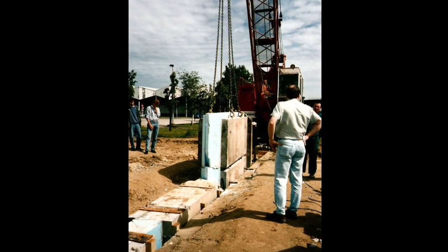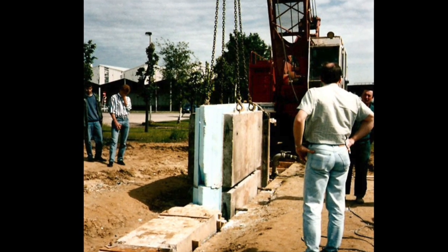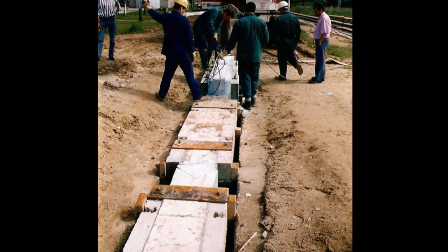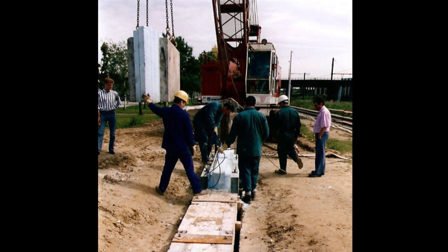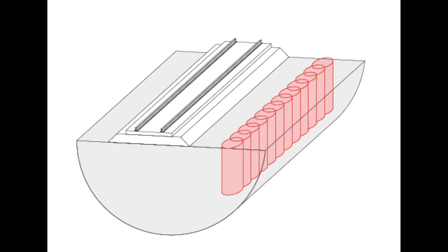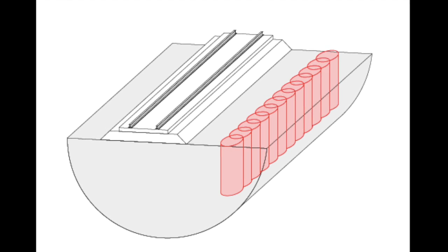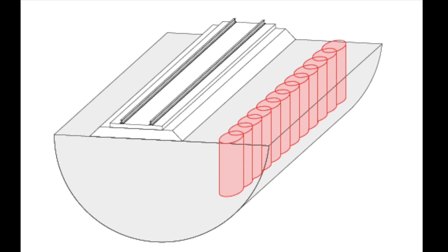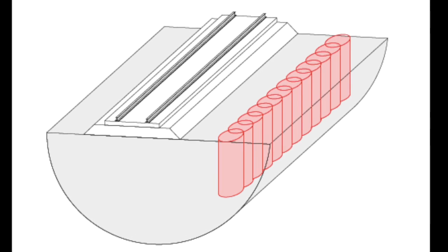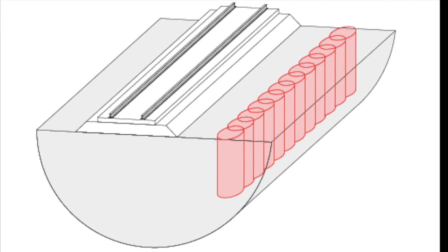Typical examples of vibration mitigation measures on the transmission path are open trenches and soft wave barriers, which aim at reflecting the incident waves in order to reduce vibrations behind the barrier. In his thesis, Pieter has focused on an unconventional type of barrier, which consists of material that is significantly stiffer than the surrounding soil. He has demonstrated that such stiff barriers behave fundamentally different, as they do not reflect but block the incident wave field.